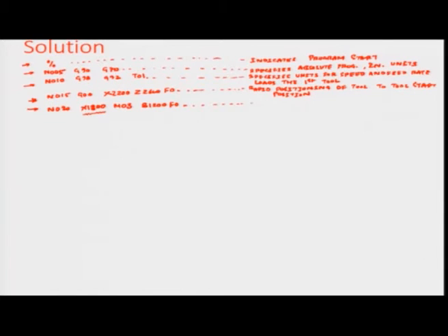I will just write this down as: position tool to remove 0.1 inch of part diameter and start the spindle. And so, with everything else ready and the workpiece rotating, you can possibly give a feed.